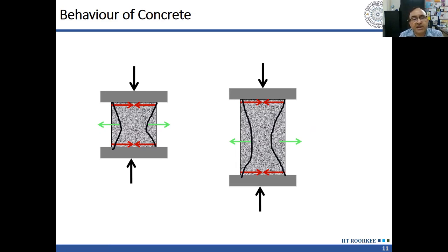And that's why when we are doing our designs, you remember in calculating the concrete strength, we are using a factor of 0.8 and another factor of 0.85. This 0.8 factor and 0.85 factor, multiplied together, give us 0.67. And 0.67 we divide by a factor of safety of 1.5 and we get 0.446. So here one factor corresponding to the end friction effect is included, which corresponds to the error in testing of the cube. That error is not there in the cylinder.